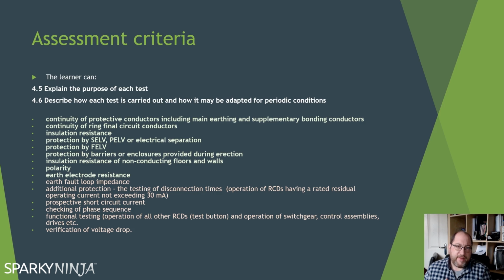And the last one there, the verification of volt drop. From an initial verification perspective, the verification of volt drop is confirmed with the design. The designer has calculated cables, sizes of conductors, lengths, and he's accommodated volt drop in his calculations. So all you've got to do to verify volt drop from the initial verification perspective is verify the design has been met. If the design has been altered, cables are longer, cables are smaller, these two problems will create a concern for verification of volt drop, and you should really get that re-verified by the designer.